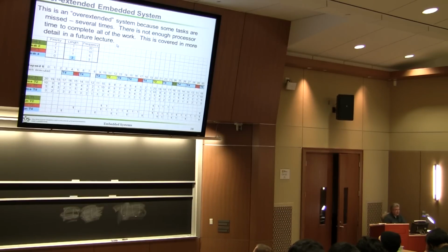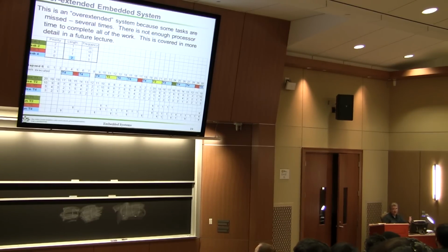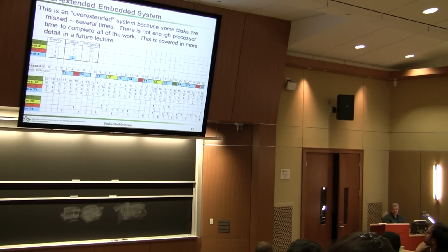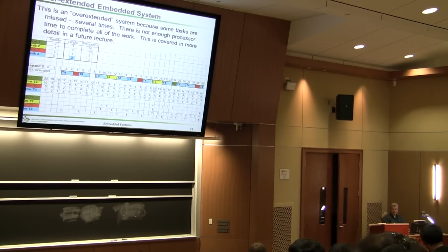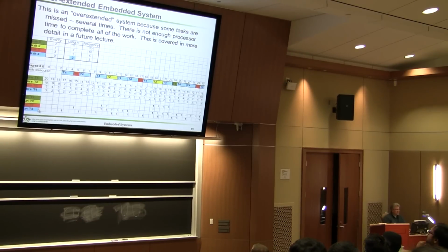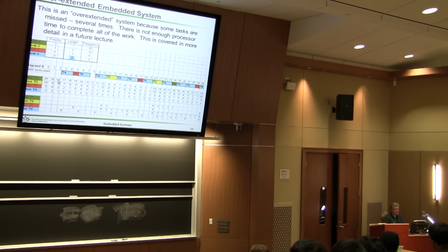Now, what are the things that actually were important from this? What do you think the interrupt service routine would affect here? Do you think the interrupt service routine would schedule the task? Usually you want to keep tasks out of it, or execution out of interrupt service routine. But what is an interrupt service routine really good for? Not computation, but setting flags, setting variables. So in this case, what's a variable that changes? Well, right here. This run is something that can be changed, and something that's really simple is decrementing.